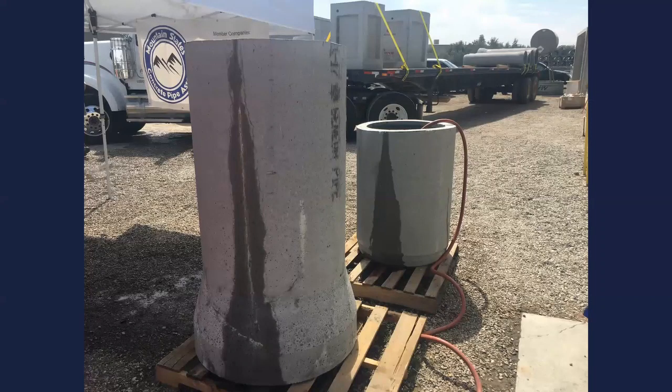The pipe that we filled up the morning of, it was leaking at a rate of 2 inches every minute when we first filled it up. And by the end of the day, it was still leaking at a rate of about 1 inch a minute. So it was leaking out. And you can also see, if you look on the right-hand side of the far pipe, that not only is it leaking out of the front where the main crack is, but there's also cracking on the side of the pipe that's leaking. But the larger pipe, that's all dried out and it's completely healed on that side.